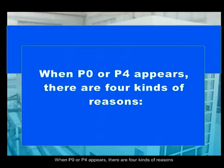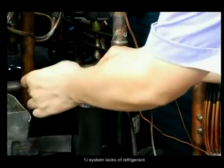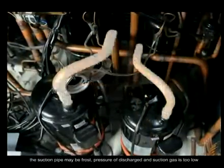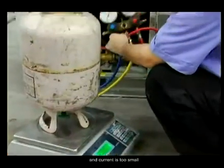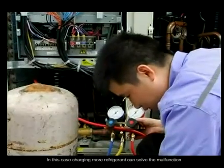When P0 or P4 appears, there are 4 kinds of reasons. One, the system lacks refrigerant. The temperature on the top of the compressor shell and the discharged gas is too high. The suction pipe may be frosted. Pressure of discharged and suction gas is too low, and current is too small. In this case, charging more refrigerant can solve the malfunction.